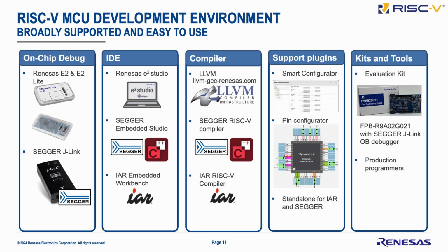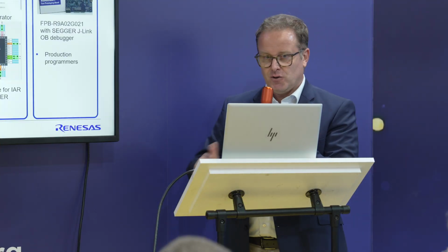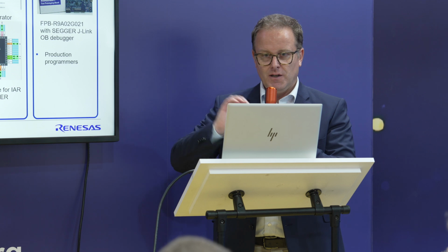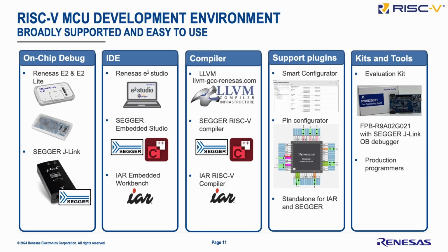To avoid the blank page syndrome you might have, where do I start now to configure my application and start writing code, we have a plugin integrated into E2 Studio, which is called Smart Configurator. With this plugin, you can basically set up everything from low-level IOs up to clocks, system-level settings, configure the peripherals that you need to use, and also auto-generate the drivers. So basically, everything below the hardware abstraction layer is already available for you with a few clicks.